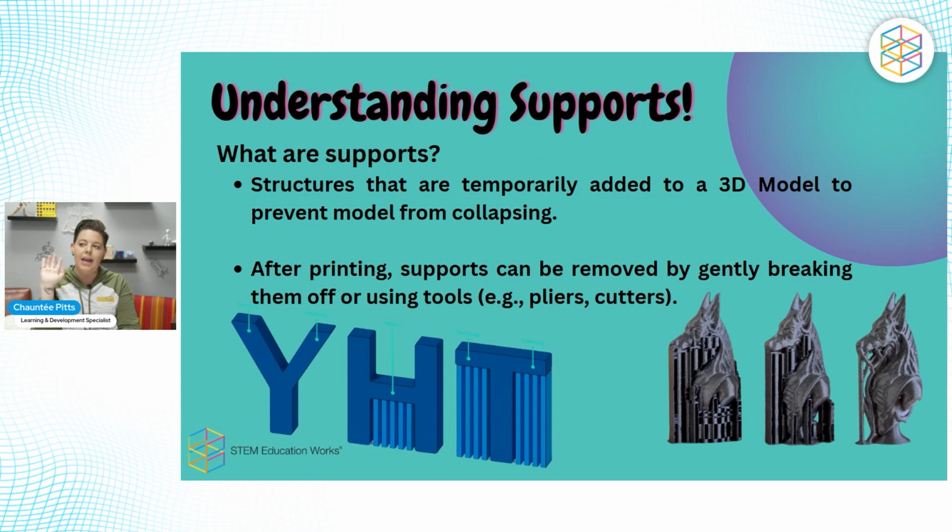So basically what I do with supports is I use the YHT concept. Again, you have to look at everything the kids create as layers. It's going to get printed in layers and it's going to build off of those layers. So H has that bridge in between. It might not be able to be supported by that. And you might have to put support underneath it to keep it from collapsing on itself. That's the reason that supports are important. So I usually have the kids or I will look at it and say, actually, that can't stand on its own without something holding it up. And that is how that works.